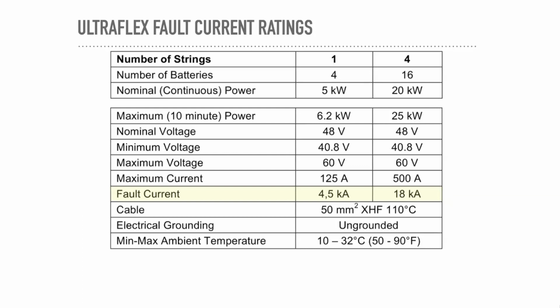So getting the information from the battery manufacturer about bolted fault current, at this point, I've found there's still a poor understanding of what that requirement is. And if you find yourself in a position where it just seems too big, make sure that they're calculating it based on what is accessible, not what's inaccessible within the product.